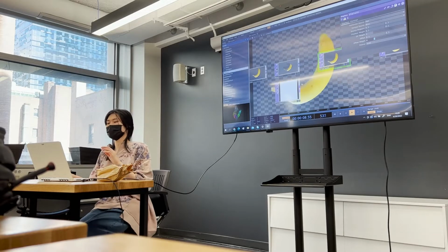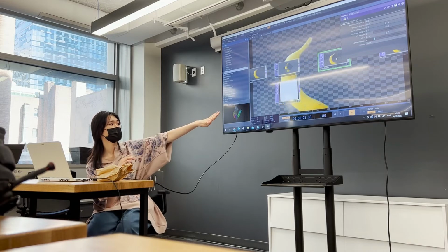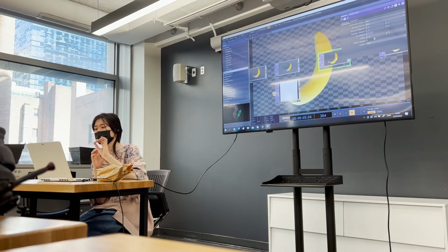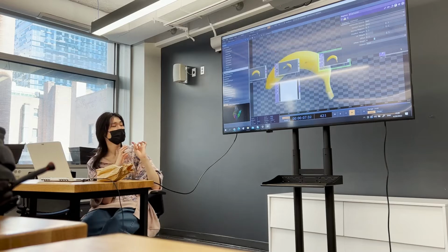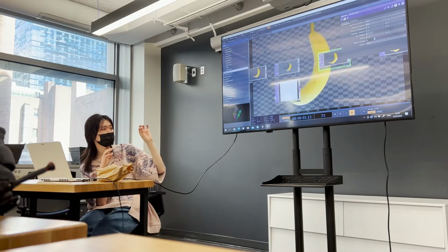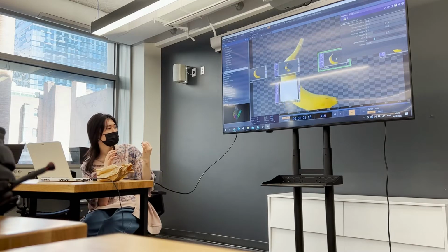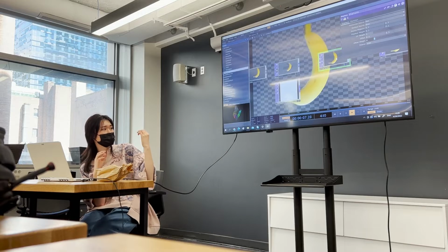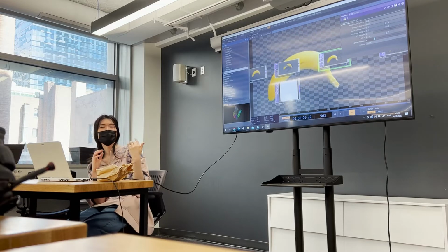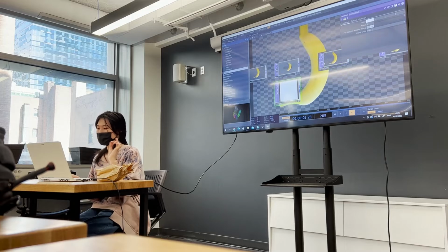So how the displace node works is that for every pixel in the original picture, it locates the pixel at the same location in the second input and uses that pixel value to displace the first picture.